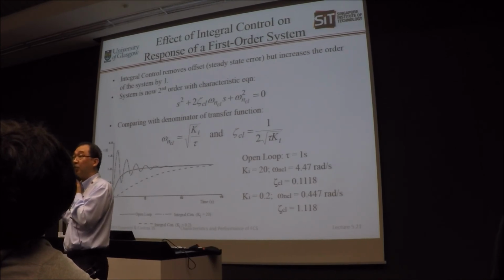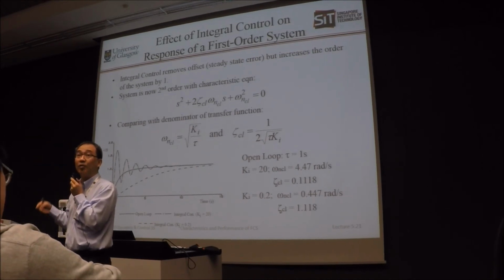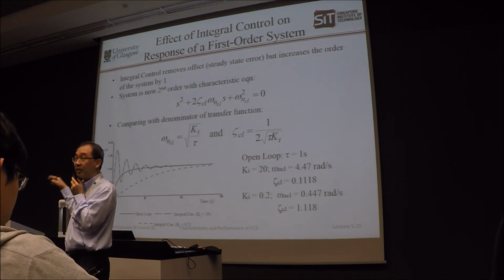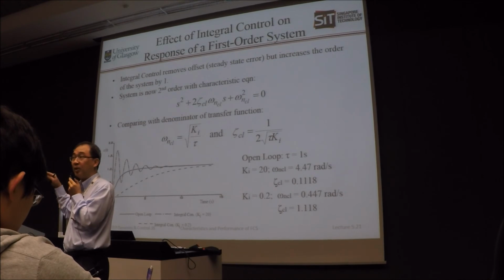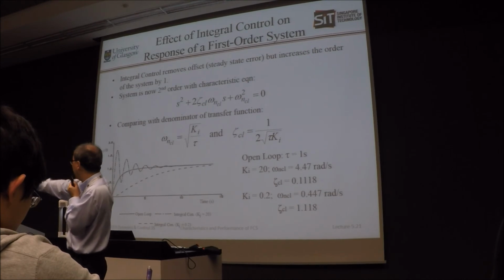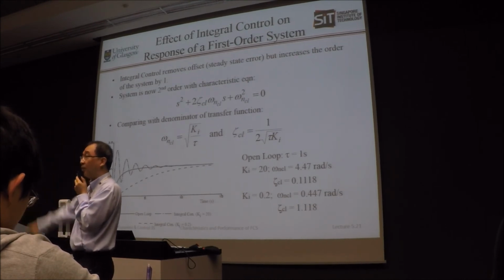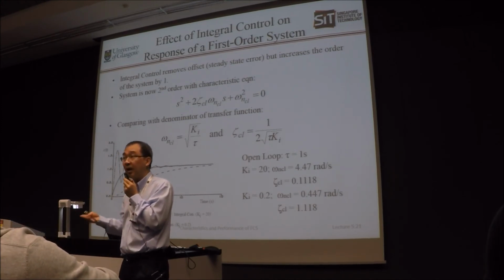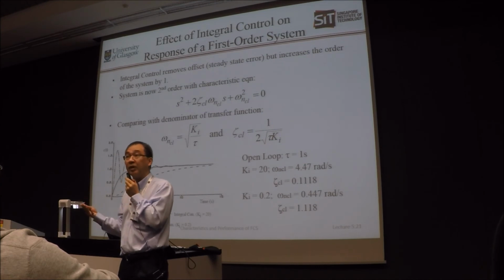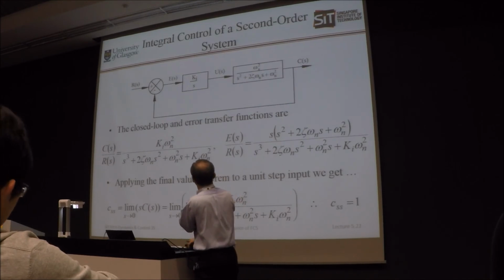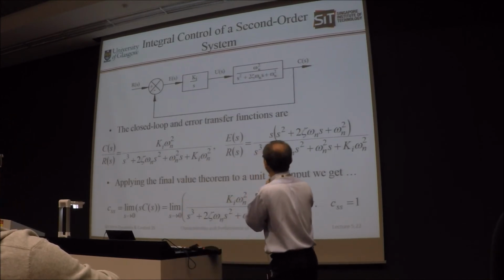Undesirable because if you imagine your structure being subjected to such a high overshoot, can your structure actually take it? You can imagine that if your wing is going to go through such a high fluctuation when you hit turbulence, can your wing withstand it? Your final value is here, then you go out 60-70% overshoot. Certain things you design for, but if you're not designed for it, structurally, it's going to fail.